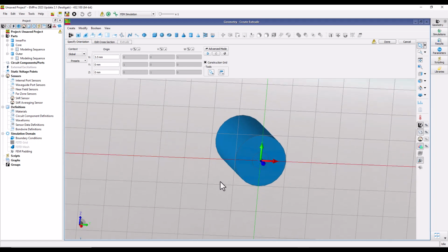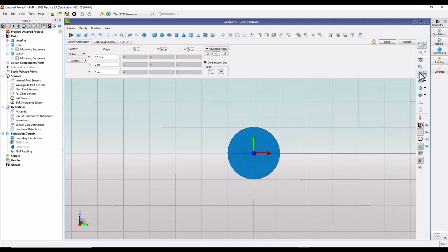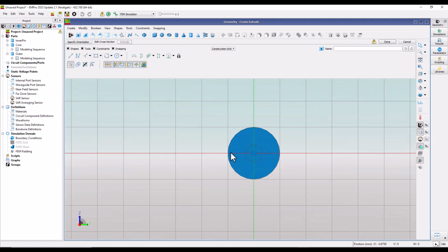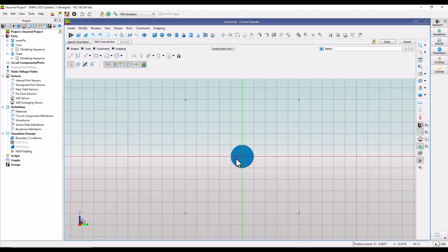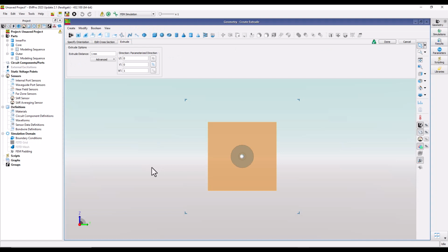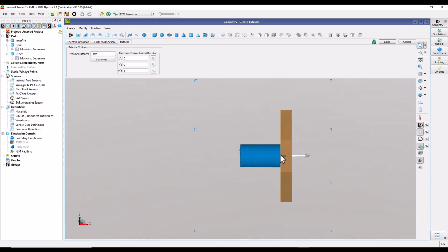So this is basic 3D drawing fundamentals, which I assume you already know if you have used a lot of other 3D tools. Now here I can use this rectangle, and then depending upon how big or how small a flange you want, you can draw the flange, and then finally go to the extrude tab, and here you can either extrude it in this direction, which is actually the reverse of what we want because your center pin is here, but you can pull it back.